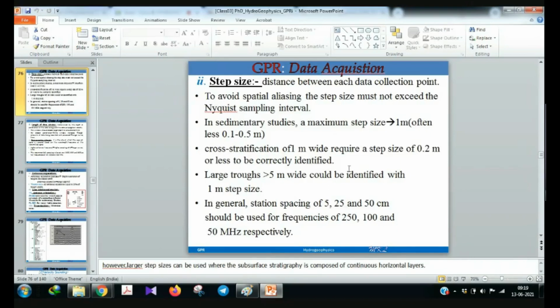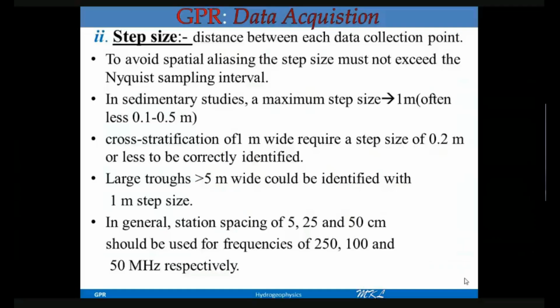For cross stratification, if you are going for cross bedding delineation, you will require a 0.2 meter station interval. That can be useful for mapping the subsurface. So this is a very important part, step size.